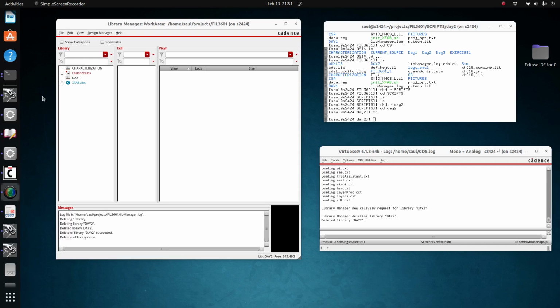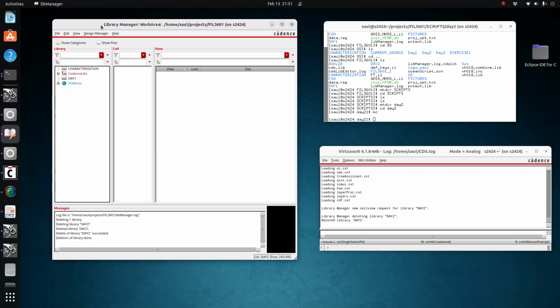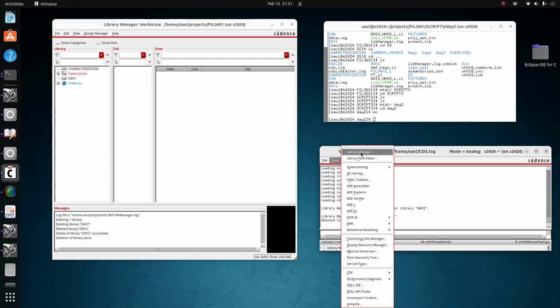So, hello everyone. This video will teach us how to start using Cadence Virtuoso and run simple simulations. First, we will create a library. For that, we have the library manager. If it is not open, we can call the library manager from Tools, Library Manager here.